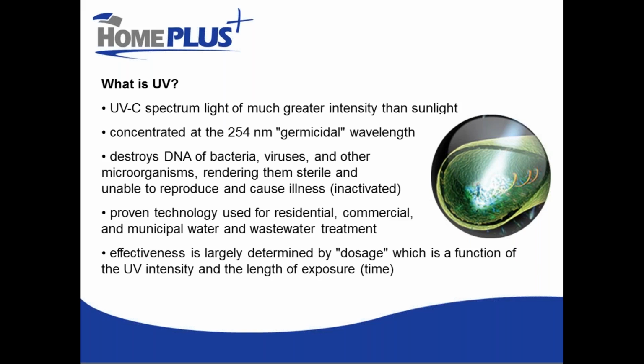And essentially what that UV light is doing is it's breaking and damaging the DNA chains inside the microorganism, rendering it unable to reproduce. So we don't generally refer to this as killing bacteria or killing viruses. We typically use the word inactivation. We're sterilizing or neutering the bacteria and viruses and other microorganisms so they can't replicate, and if they can't replicate, they can't cause illness.